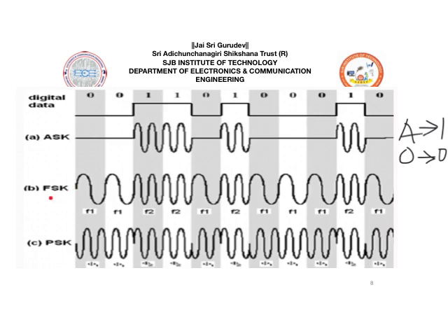Now, moving on to the next type, which is called FSK, frequency shift keying. As we discussed, in frequency shift keying, if there are binary values 1s and 0s, whenever we are considering the binary value 1, we are taking one frequency, let that frequency be f1. If we are considering the binary value 0, we are considering another different frequency. Let us represent that frequency as f2. Two different frequencies will be used. For binary value 1, we are using the frequency f1. For binary value 0, we are using the frequency f2.